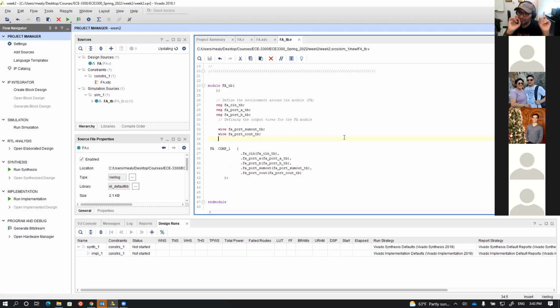Did you see? I made a mistake intentionally, to show you that fixing it, first of all, in the test bench you don't have any input output ports. You have to define what wires or registers you will need, and then you start inserting those inside the ports of the input and output and inside the module. So far, so good. My chip is called FA, which is a 1-bit full adder, ready to accept anything going inside as input, then we can see it as an output.